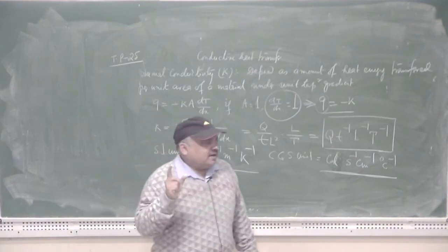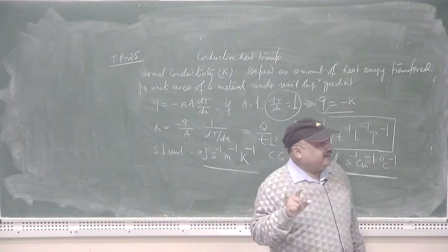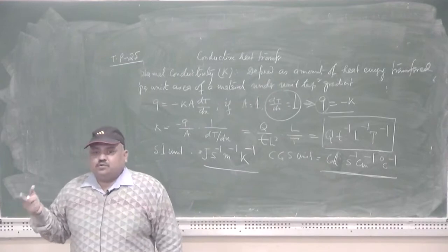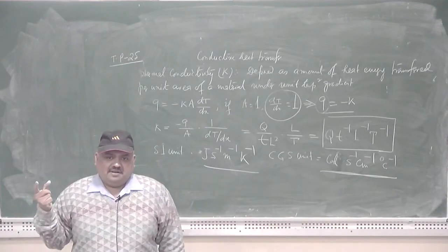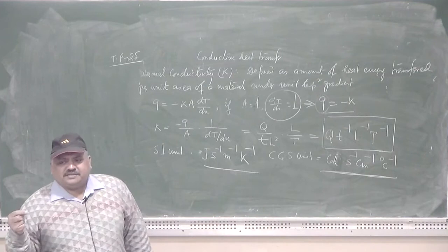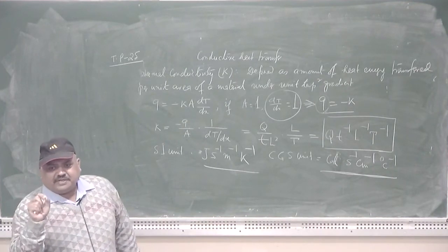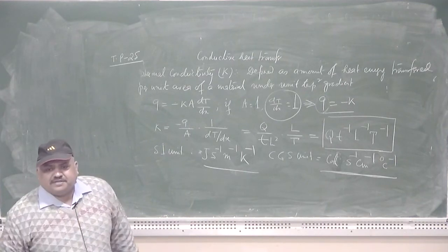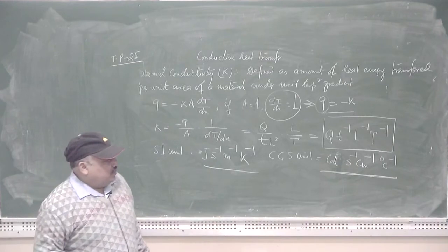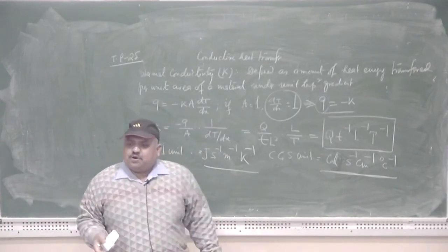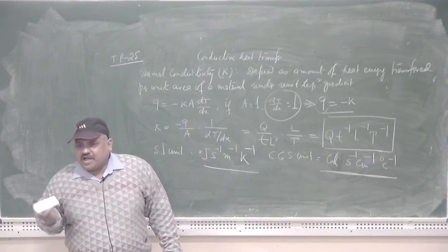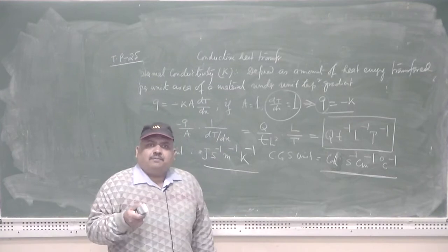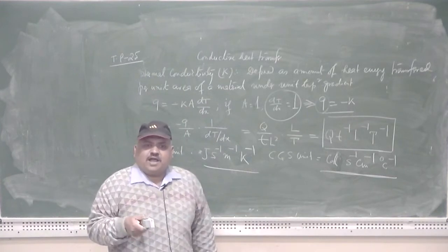Let us suppose an aluminum silicon alloy melts at 675 degrees centigrade. If you carry out the melting process to 715 degrees centigrade or 700 degrees centigrade, it means you have given a superheating of 35 degrees centigrade and 25 degrees centigrade respectively. So, a proper choice of mold material as well as a proper choice of the superheating can easily dictate the desirable property in that particular metal or alloy.